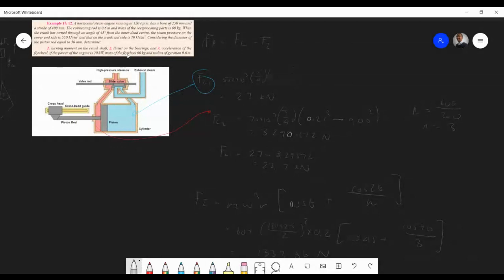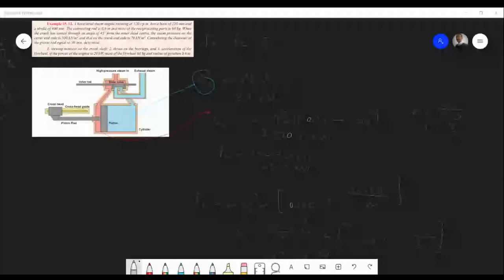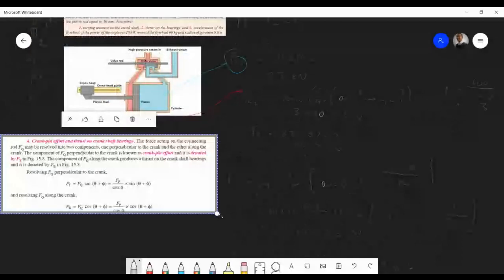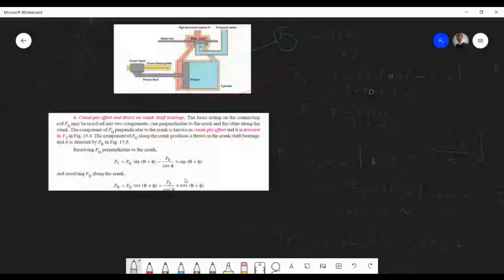Oh, yeah, it does actually exist, and I guess I didn't actually talk to that. Let me quickly show you. Yeah, it does come out. Funny enough, it doesn't always come out, but it is there. So I'm not going to work that one out. Obviously, that's not the point of what I was trying to show you, but I'm making you aware that if you are working it out, then you do see it. I wouldn't say focus on it, but thrust on the bearings, if it does come out, is just FP divided by cos phi times that over there.